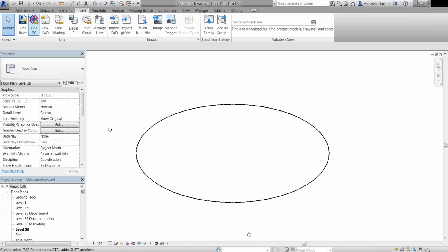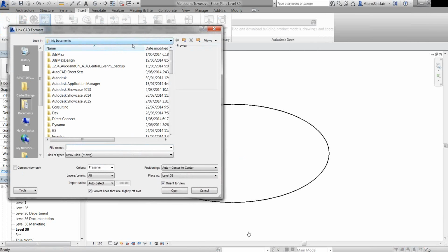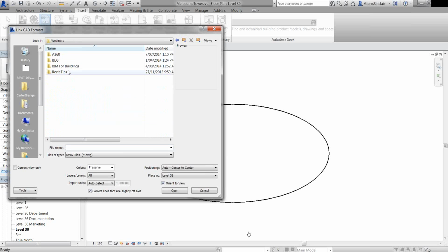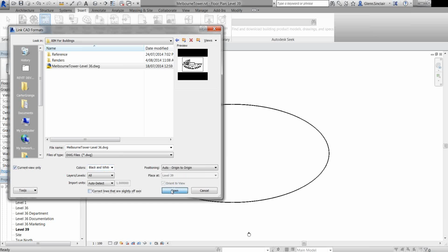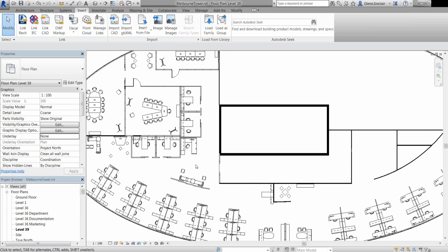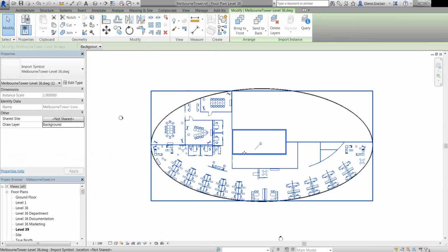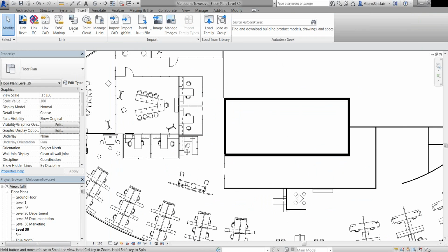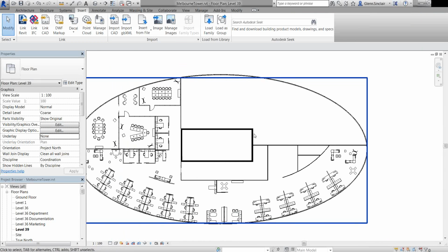One of the workflows, I guess, that we could use is to link a CAD file, if you've got another team working in AutoCAD, or if you had existing bits and pieces in your AutoCAD library. We can use that information. We don't have to just throw it away, going straight to Revit. So a pretty common workflow is to bring that in as a CAD file for display, in context of our 3D model. Obviously any facade changes we're keeping up to date.